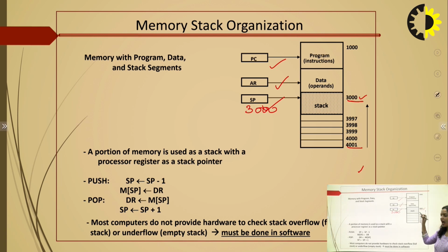So insertion and deletion in this stack will take place in the form of last in first out. So data which is lastly inputted to this particular stack will be first to get out of this stack. Now let us have a look at how this operation is performed in your memory stack. For the push operation, as we have these addresses in decrementing order, suppose I want to insert an element A at this 4000 location.